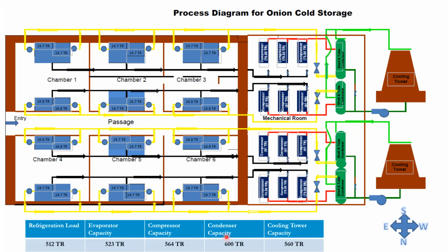Based on the availability of the equipment, there must be a slight variation between the capacities, but it should be in increasing order, because the condenser capacity must be maximum. It should meet the maximum requirements, because here more area is provided, so that even in some cases when the water temperature increases, the surface area will compensate the condensing temperature.